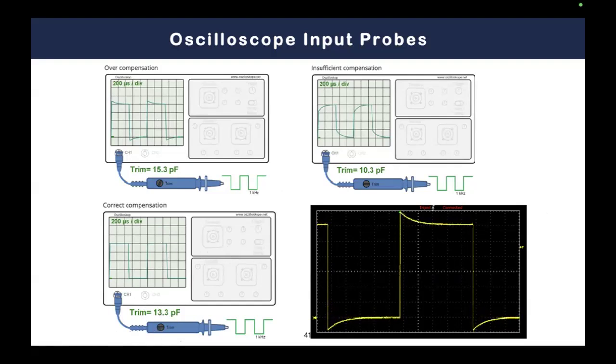Again, the question someone can ask you this in an interview, and maybe in the lab discussion exam or whatever: why are we using a square wave in order to calibrate an oscilloscope? Simply because we are seeking the high frequency components. If you have a sinusoidal wave, most likely we will not face these problems because you have only a single frequency component.